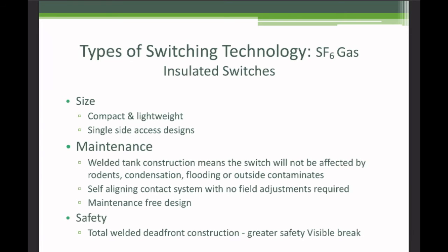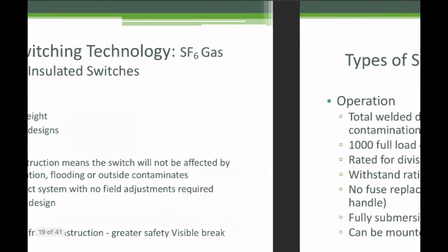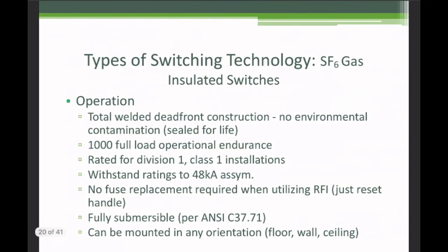For air-based switchgear, it's easy to do. It's out in the open. For oil-based switchgear, it was impossible because the oil isn't transparent. After a couple operations, it's too opaque. You can't see through it. There's no point in having a window there. With SF6, we get our visual open back, which is a major step forward for safety.